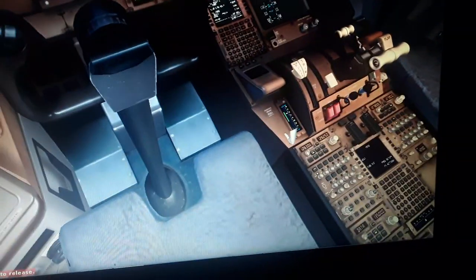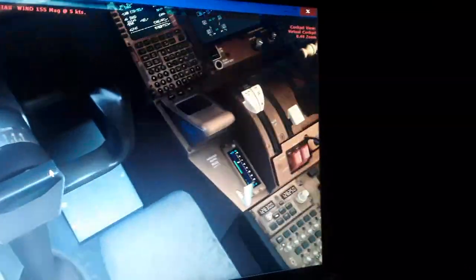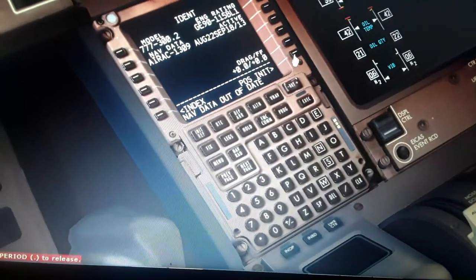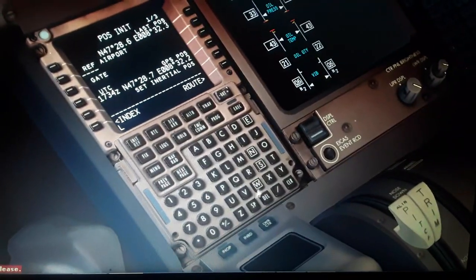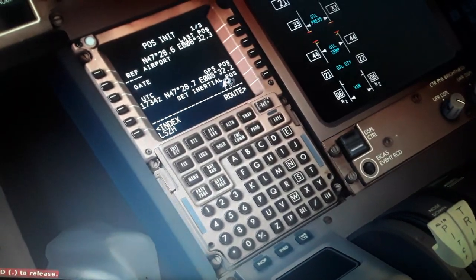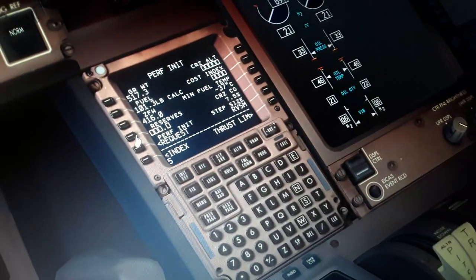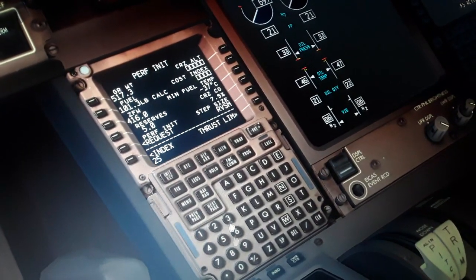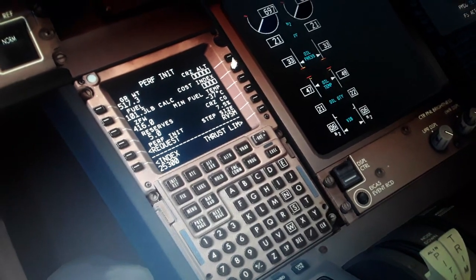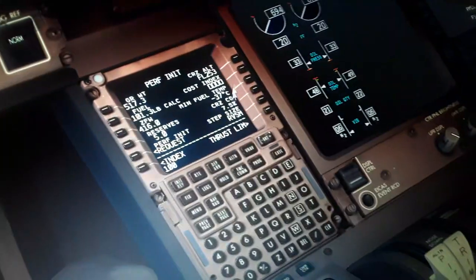We only need one small step here, and maybe we have like 15 minutes for flying. So we need to set up the flight management computer, the FMC. We go with the inertial reference position, initialize this airport, LSZH, set inertial position, initial zero fuel weight, gross weight, reserves 5%, flight altitude 35,300, cost index 100%.